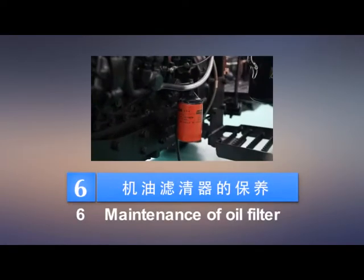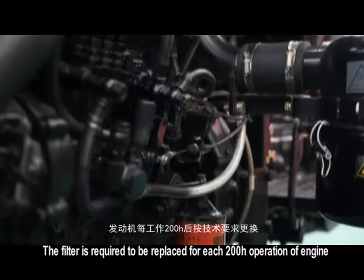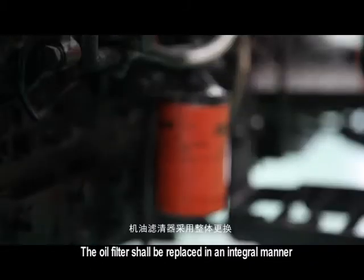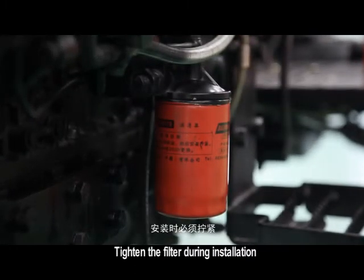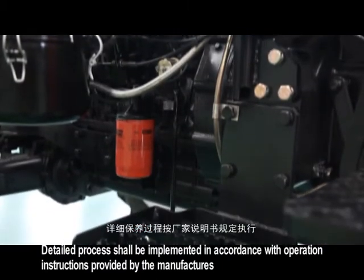6. Maintenance of oil filter. Oil filter is located at lower part on left side of the engine. The filter is required to be replaced for each 200H operation of engine. The oil filter shall be replaced in an integral manner. Tighten the filter during installation. Detailed process shall be implemented in accordance with operation instructions provided by the manufacturers.